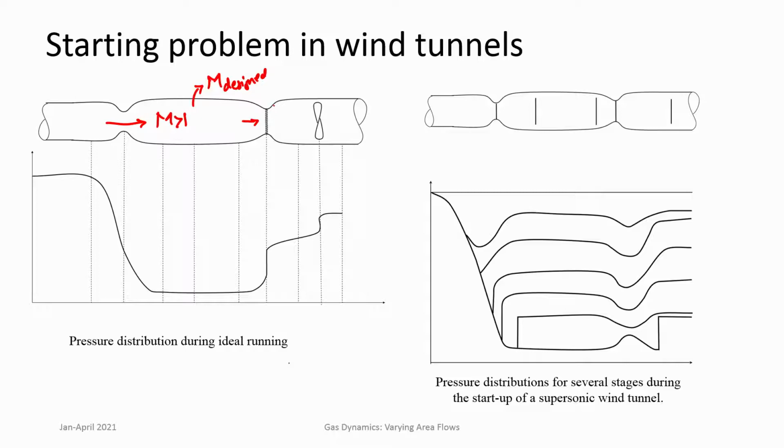If the shock stands in a diverging passage at some other point, then it would have decelerated to the minimum Mach number, but again accelerated to much higher Mach numbers, and the shock standing in the divergent portion will be much stronger. So, ideal running condition is when the shock is at the minimum area of the wind tunnel diffuser, a CD diffuser.